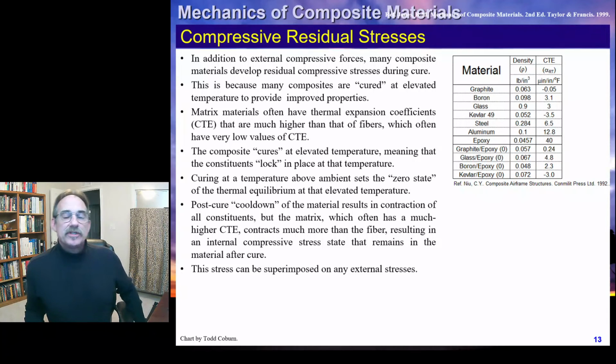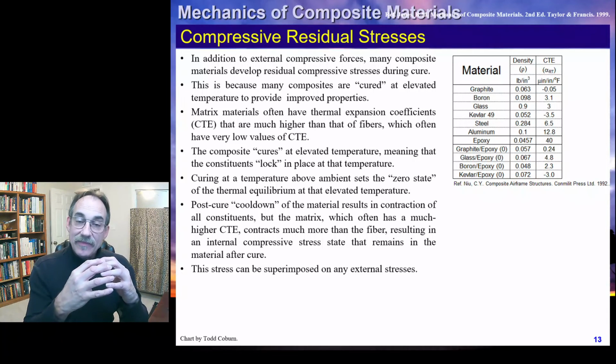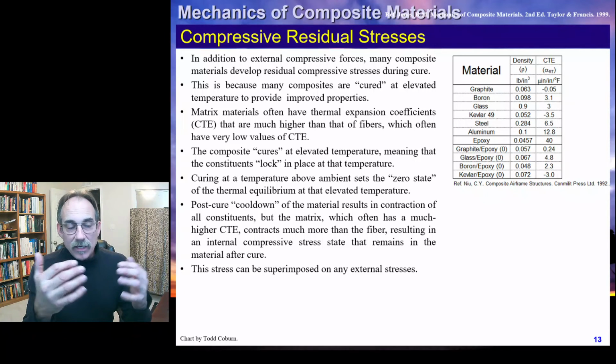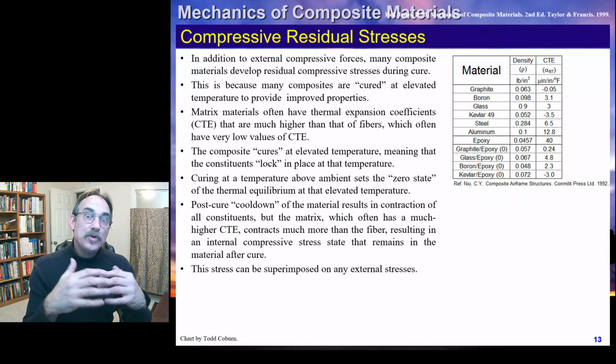And a lot of times, as long as we're curing these and then testing our cured part, we don't necessarily need to superimpose additional residual stress on top of what we already think we have if our test data already includes something that's been cured in the same manner.